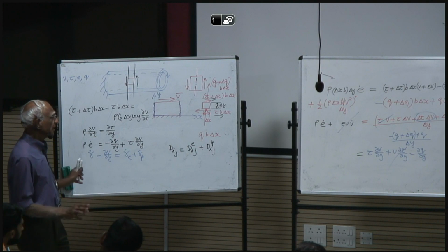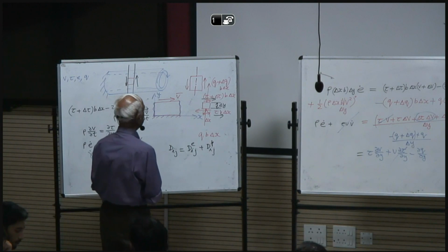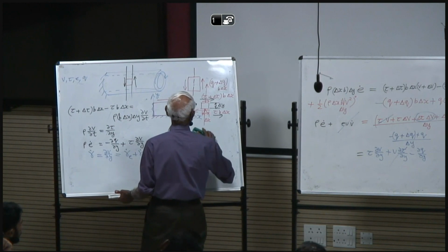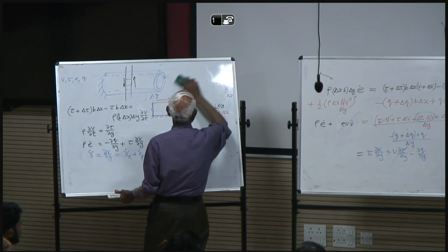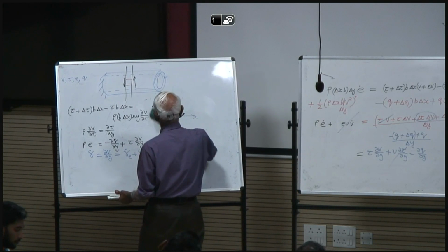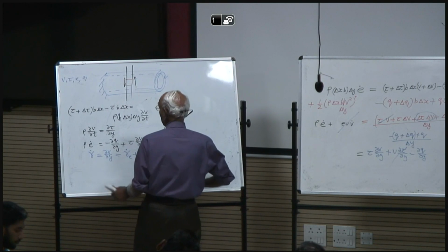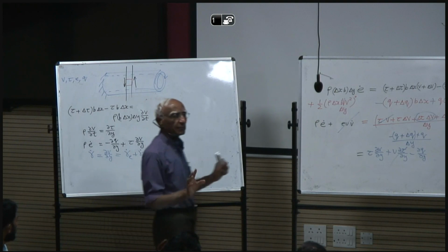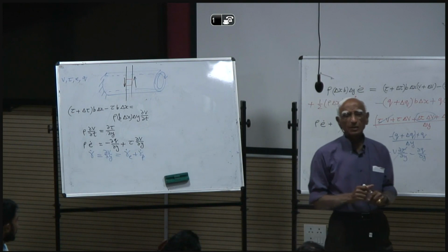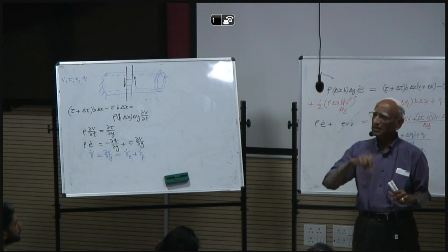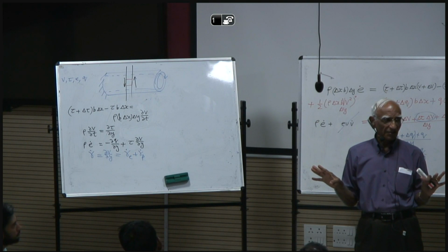Okay, in plasticity now, we need to write the constitutive equation here. The stress evolution depends only upon the elastic strains, because you are required to stay on the yield surface.